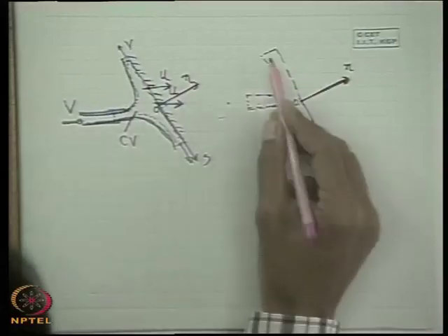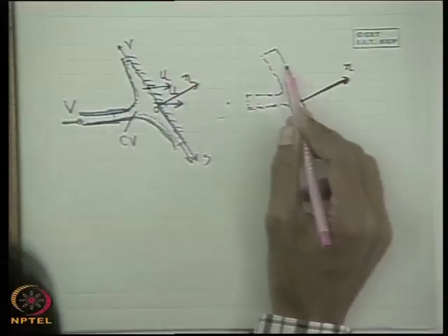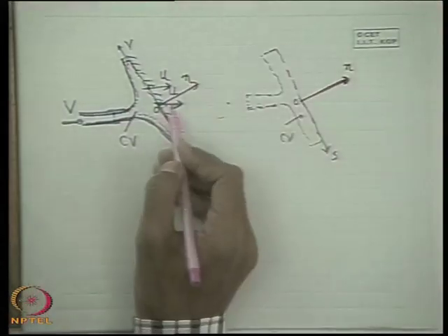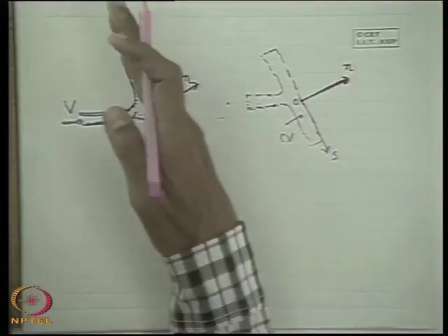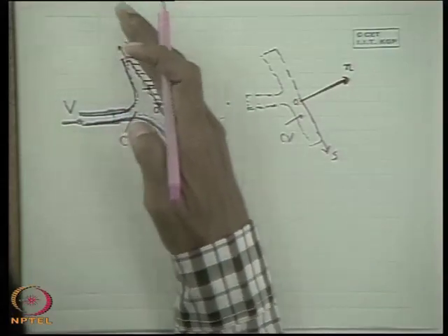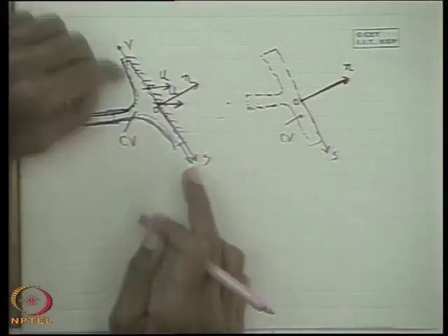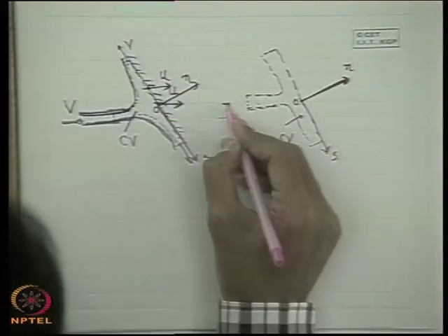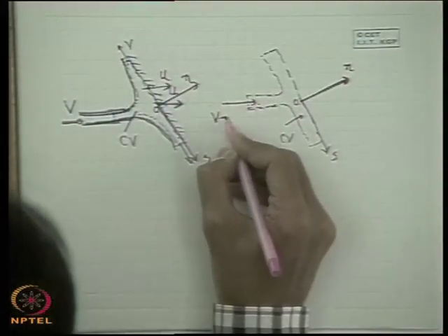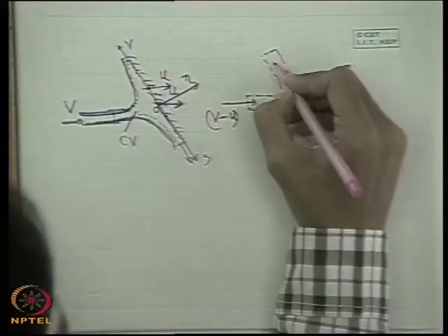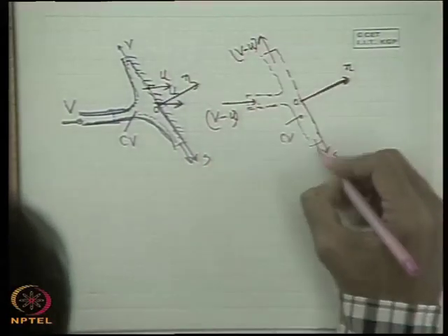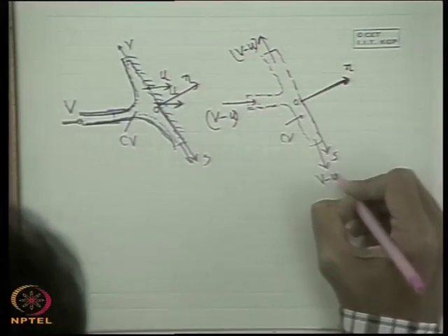So, therefore, this will be with respect to the control volume. That means we make the control volume fixed, or the other way, we give an opposite direction velocity to fix the plate. That means it will be similar to the earlier case of an absolutely static plate with changed values. In that case, the fluid will come in with V minus u, and the fluid will also leave with the velocity V minus u.